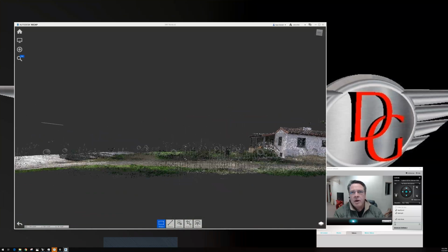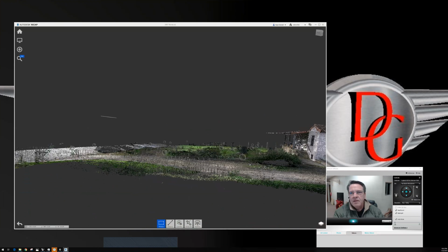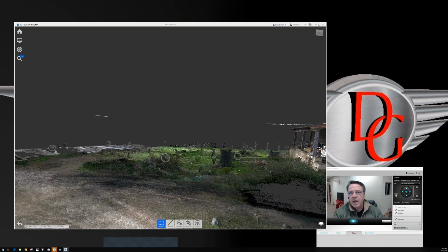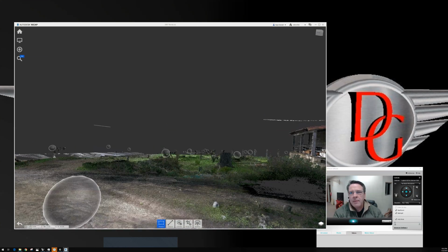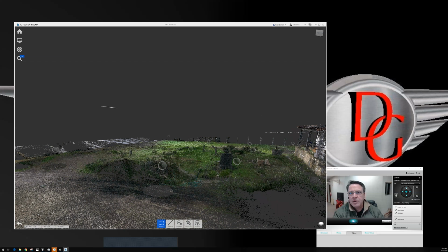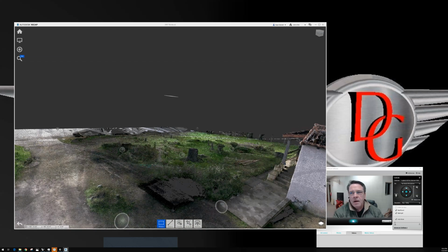When you look across, you're still seeing fences, and the big thing is a lot of this foliage. What has to happen for us to do the topo map is we have to cut as many of these shrubs down, and bases of the trees, as close to the ground as we can. The reason for that is when we go to create a surface off of this, it will create noise.